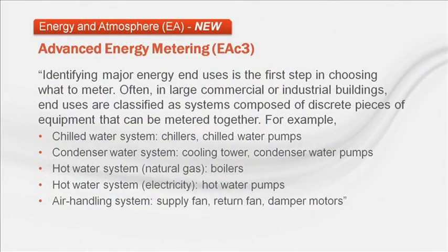Here's an excerpt from the LEED V4 reference guide that gives useful direction. It states that systems, rather than discrete pieces of equipment, may be metered to achieve this credit. So in this case, the chilled water system and perhaps the condenser water system should be metered.